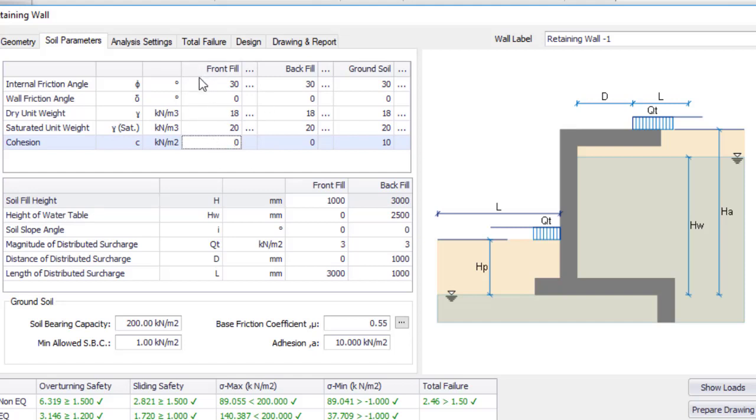Then you can leave this as default. These are actually defaults for sand. But if it is clay, then you have to just check your books and then put in the right value. Okay, now let's deal with the way it is being filled.